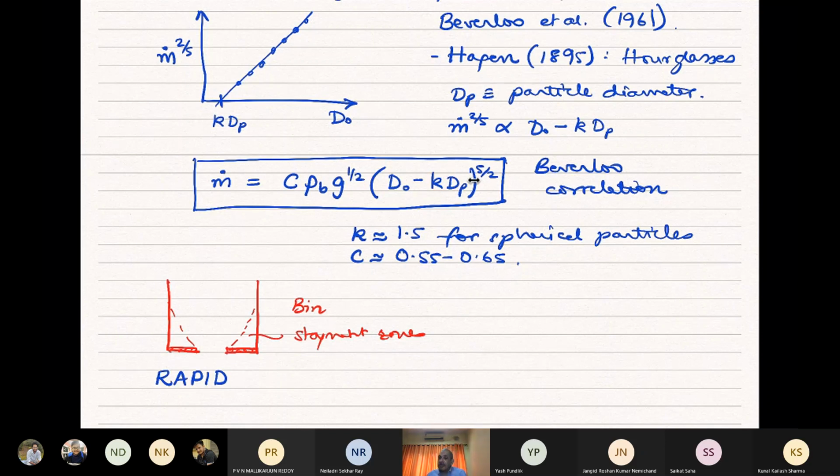But that choking is something different, because when the particles form an arch, usually there is some level of cohesion between the particles so that you can form such a huge arch. If the particles are very freely flowing and they don't stick with each other, then the arch formation happens only if the orifice diameter is of the order of 6 particle diameters. If you go more than 6 particle diameters, then for smooth particles, you'd never form arches. But in practice, because the particles are slightly sticky and they have some cohesion, even in very large diameters, you can form an arch.